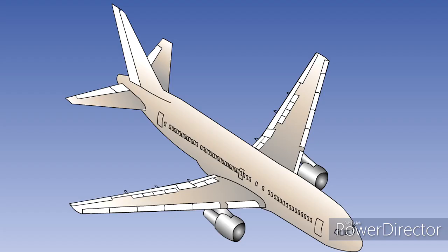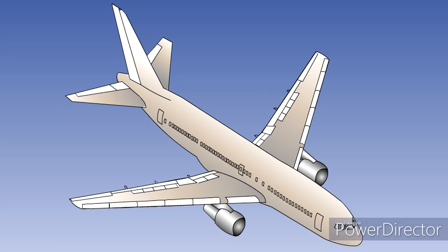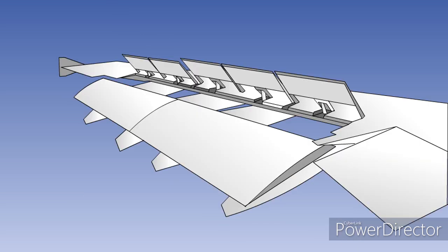We will have a look here at a typical aircraft speed brake system, using spoiler panels on the upper surface of the wings. There are a number of panels on each wing. The Boeing 737, for instance, has 6 on each wing. The panels are hinged at their forward edge and are extended into the airflow by individual hydraulic actuators.